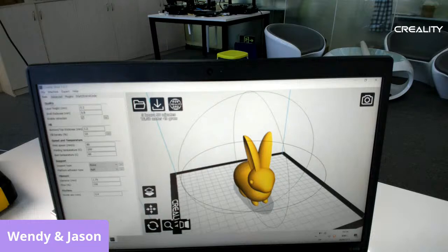From the quality section, you can change the layer height and shell thickness. You can enable the retraction as well, so it's a check mark. I think this part is very important to print. All three options are in this quality section. For the layer height, if you make it thicker, it's gonna print faster, but the texture does not look that good. So the quality is gonna drop a little bit.